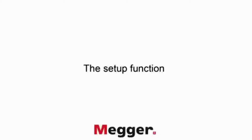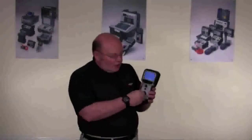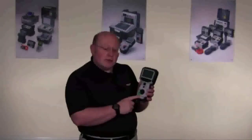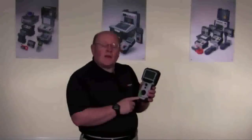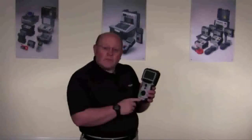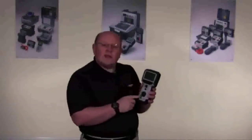Now the setup feature. On the setup position, you have access to the menu. The menu allows you to adjust the velocity factor, depending on the cable that you're using. It allows you to adjust the gain, and it allows you to adjust the pulse width, depending on the range that you're on. It also has features for adjusting contrast on the display and muting the sounder if you wish.